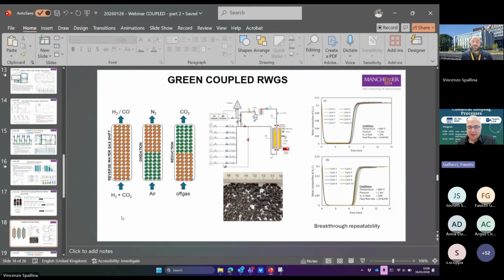Sorry if I interrupt, in view of time, the question was not that. The question is, when you use bigger particles, do you need to introduce also a particle model inside your reactor modeling? No, we haven't done it yet. You probably want to validate the kinetics, or you may need to revise the kinetics because you may have additional mass transfer at the particle scale.